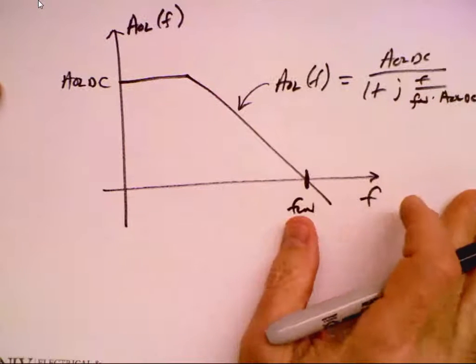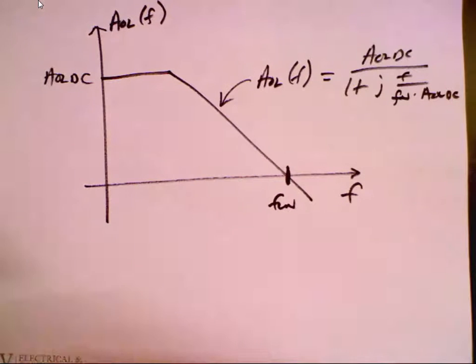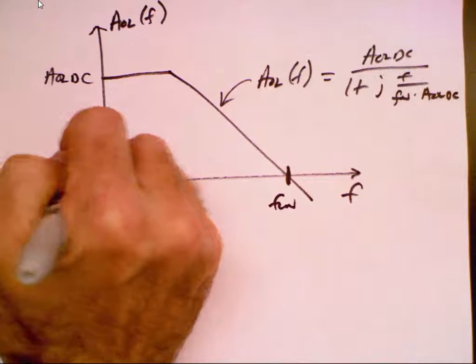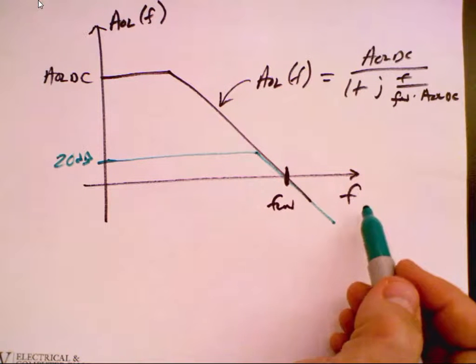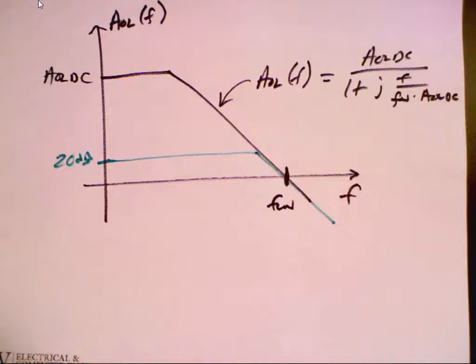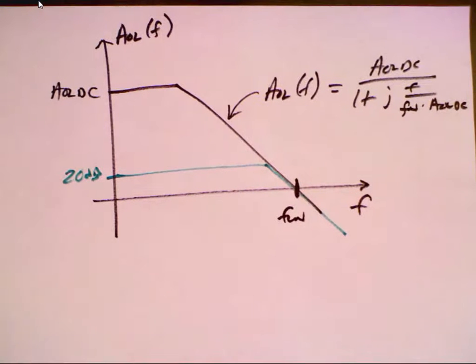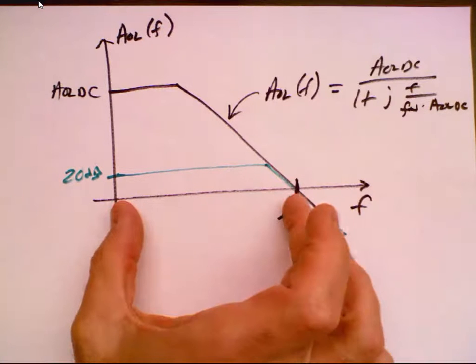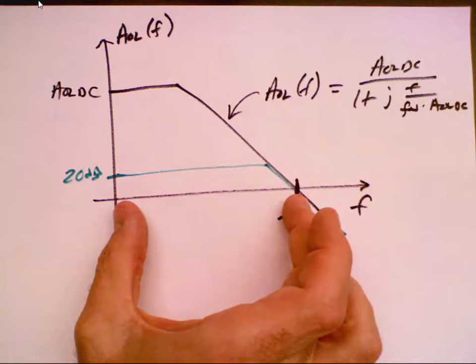And so what I'm saying now is that if I have a gain of 10 op amp, the simple way, without looking at any math, is you say, okay, gain of 10 is 20 dB. I get curves that look like this. And so they are limited by the op amp. I'm not going to go through the op amp theory. It's in chapter 3 if you want to read it. And I doubt very seriously we'll get to chapter 3 because there's still a lot to cover, but we'll see. The end result is your bandwidth only has to be F sub S over 2 for the op amp to work. Okay? Any questions?